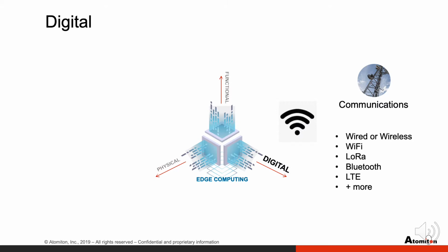Communications to and from the edge depends on hardware and software to transmit and receive data through local, short-range, or long-range technologies. Communications at the edge can be wired or wireless. In industrial environments, communications are often a challenge, with physical or geographic issues making wired connectivity difficult to implement. There are many different wireless communication protocols available, such as Wi-Fi, Bluetooth, Zigbee, LoRa, and LTE, which are common in industrial IoT implementations. Each of these protocols has their advantages and trade-offs in terms of data rates, range, power consumption, bandwidth, reliability, security, cost, and whether they are proprietary or open.